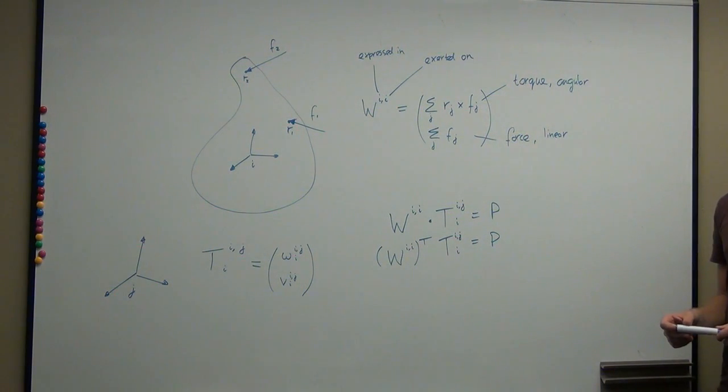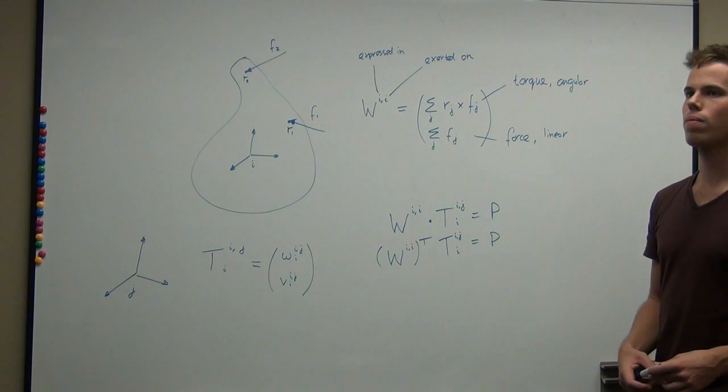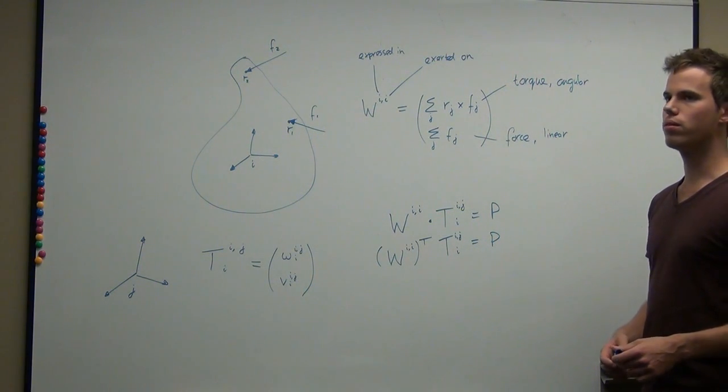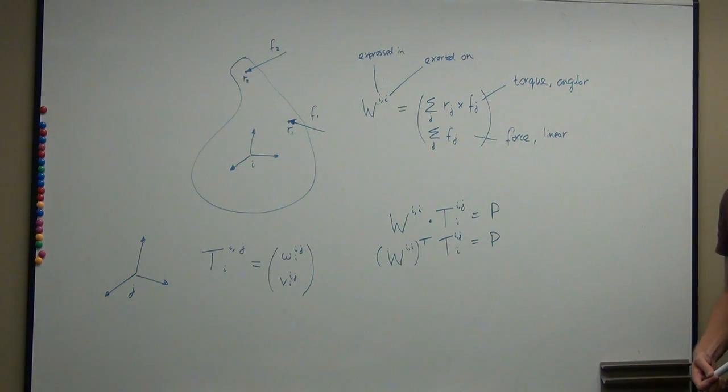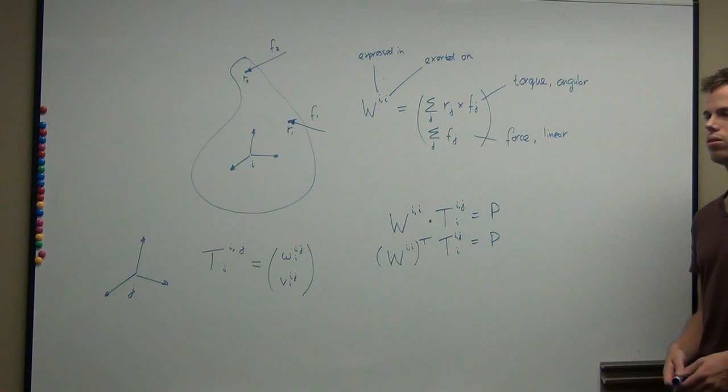Then the thing I didn't like, if I remember right, with wrenches is that there should be that third frame, just like with twists. Because it should be the frame that you're reacting from. So where the twist has the base frame, the wrench should have a base frame. So it's where your virtual actuator will be connected if it's producing this wrench. It might be interesting to pursue that notation, see if it helps. But it's just really verbose.